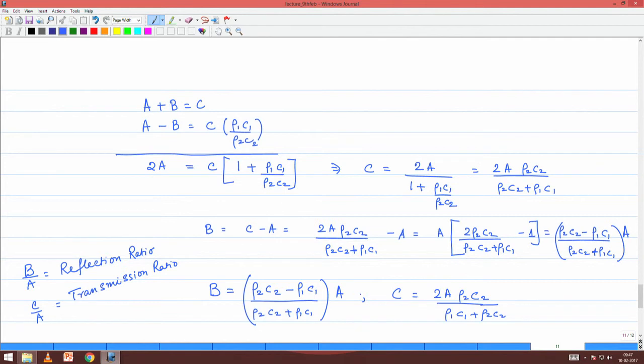In muffler design, when you have this expansion chamber kind of muffler, this is exactly what happens, that you are creating two zones with two different impedances. Just that impedance within a muffler has to be defined in a little different way, but the idea remains the same, that when you have a sudden expansion, the impedance suddenly changes and the wave sees an impedance mismatch. A part of the wave turns backwards, right. So, what happens is that the part which goes outside your exhaust is diminished, and a part of it goes backwards right up to the engine.